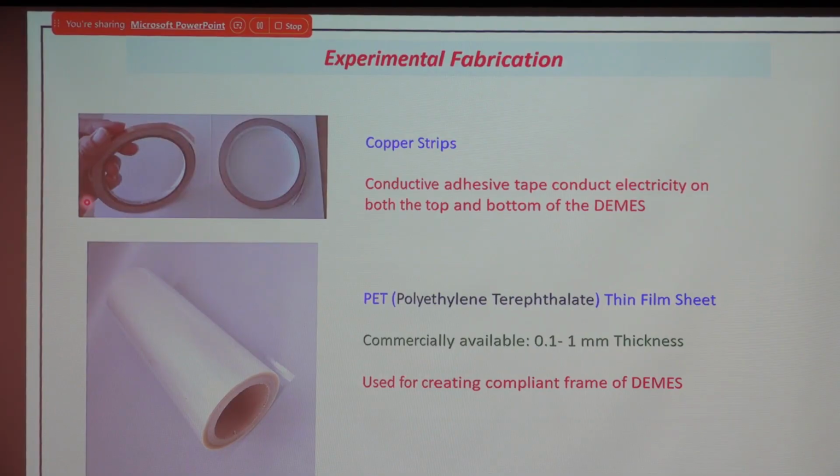You're getting my point? So on that area which is in touch with the active part, always put some carbon grease over the copper strip, and the remaining you can directly connect to the terminal. I will show you the complete picture of that, okay.